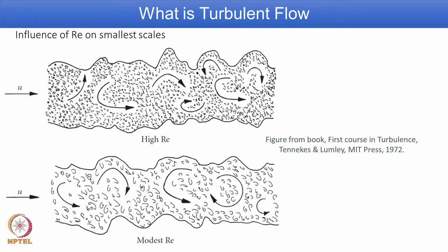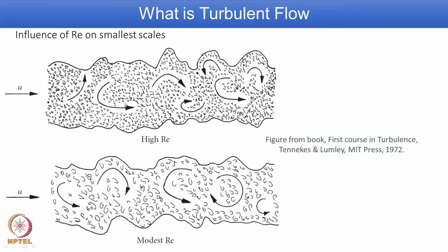We already mentioned large eddy is limited by the geometric dimension of the flow. In this case, once the jet is issued, the geometric dimension is actually the spread. So, for example, from this side to this side, this is a geometric dimension, the spread, that is a limitation. The large eddy will move between this limit and that is the motion that is possible. So, both in this case as well as in this case, the large eddy is almost the same,